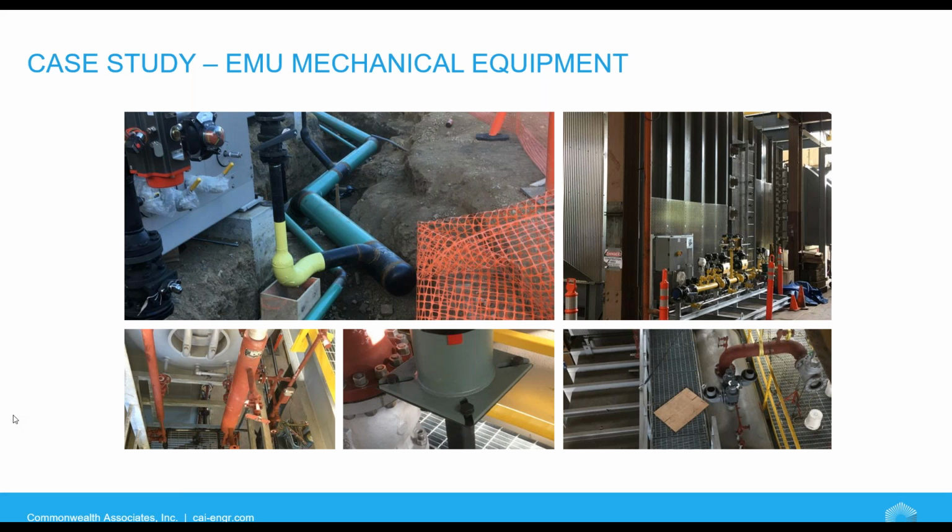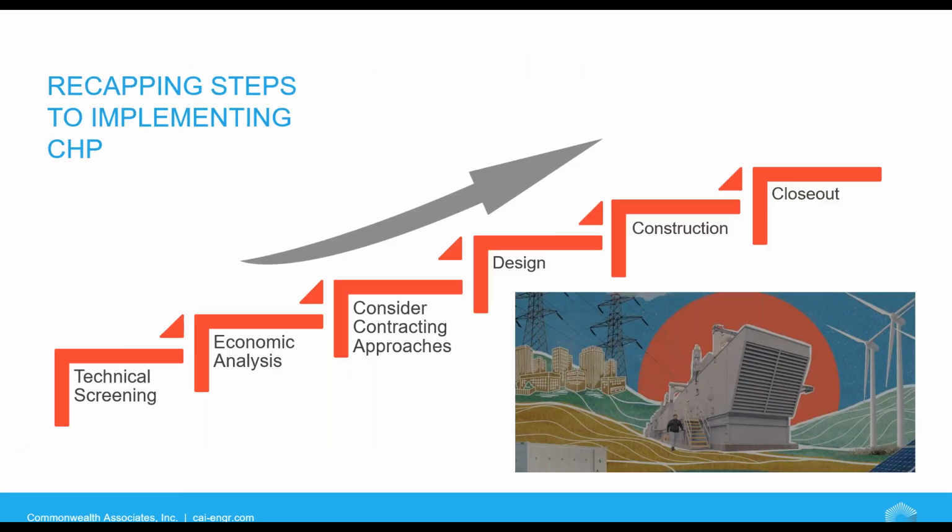In addition, steam piping will grow approximately 1 inch for every 100 degrees of temperature rise per every 100 feet. So thermal growth, if it's not controlled properly, can result in overstressed pipe and connections that could lead to catastrophic failures. And I think if we all go on YouTube, there's a fair number of these that you've seen at plants over the years. Steam piping should always be evaluated for stresses by a qualified engineer, as should any other high temperature or high pressure piping system.